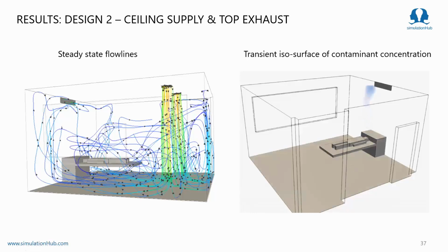So as I said, initially the contaminant is moving in the upward direction, and from there it is directly leaving the space. So this system is near to our ideal system, we can say, because another objective of the isolation room is to remove the contaminant on-site itself. It does not allow it to spread. So this flow behavior does not allow it to spread in the room.